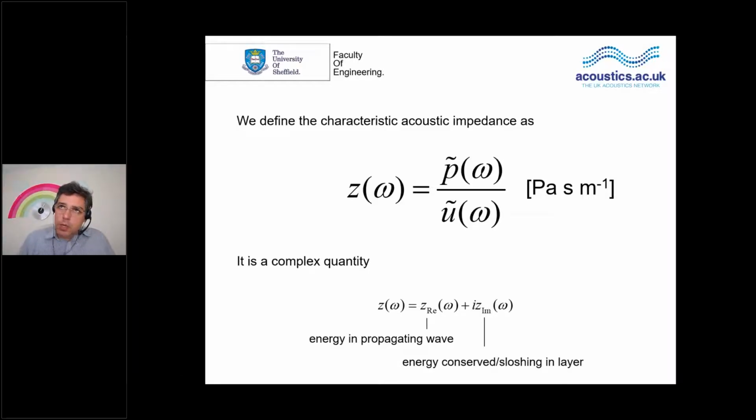And this quantity is usually measured or predicted for a range of porous materials, and can be amazingly useful because it determines, for example, in noise control applications, how well materials are able to absorb sound, or it can be used to determine characteristics of porous media from acoustical data, which are hard to determine otherwise.